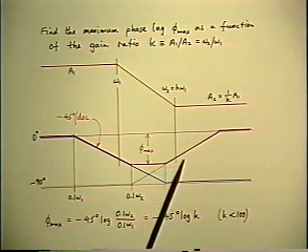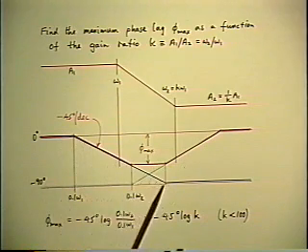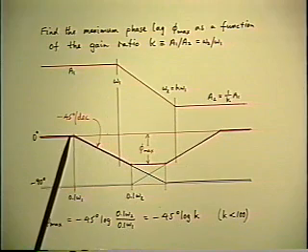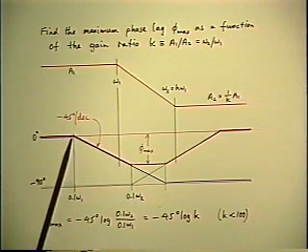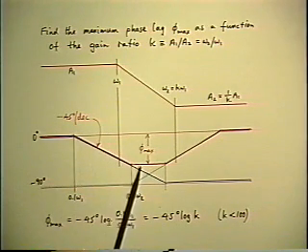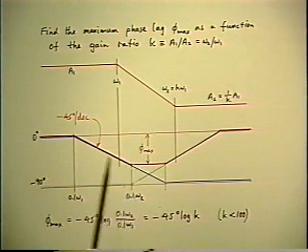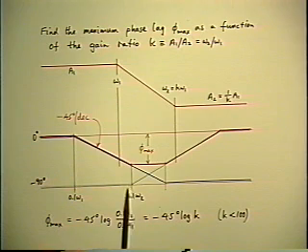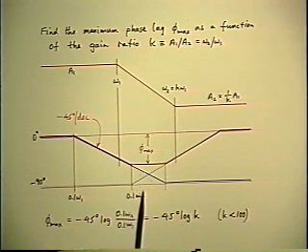That's a very simple little problem, because the phase asymptote for the pole remains fixed if the pole remains fixed, and it starts at 1/10 of the pole frequency. The maximum lag is simply the value of the phase of the pole at the frequency where the overlap begins, which is 1/10 of the zero frequency.